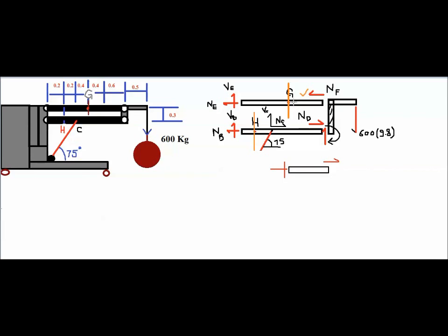We have to analyze the forces which act on the bar, not by the bar, right? So this bar was pulling up this L and stopping it from rotating downwards, and therefore it is pulling it by that force. But it's Newton's third law: every action has an equal and opposite reaction. So that is the action that it is doing onto this L bar, and the reaction generated is on the opposite side, which is trying to pull and tear it apart onto the right hand side. So the force is acting in this direction.